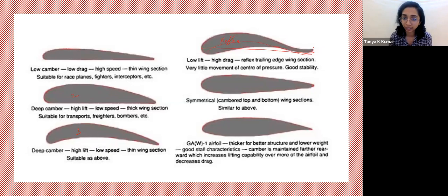It also has higher drag, but we bring this into play to ensure that you have zero or positive Cm, not Cm at AC, okay? That is required because we require our aircraft to fly. We don't need any moment carried to the aerodynamic center. We also prefer our aircraft to be trimmed at positive angles of attack.